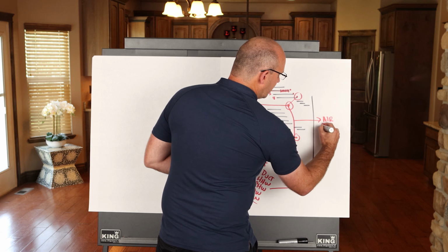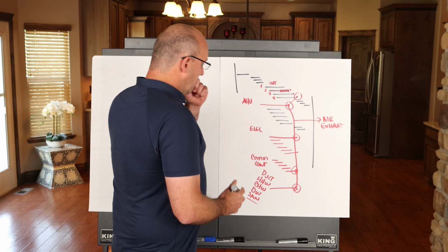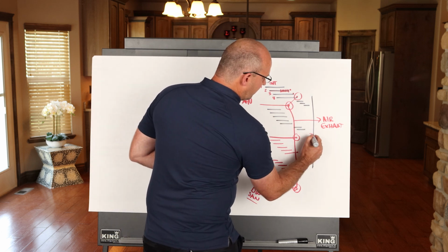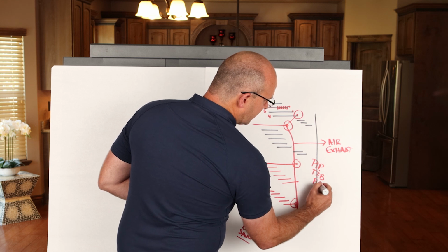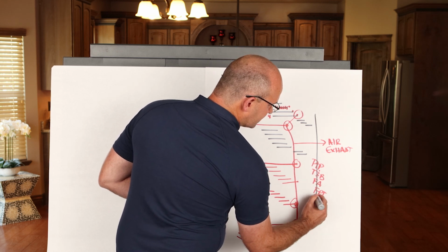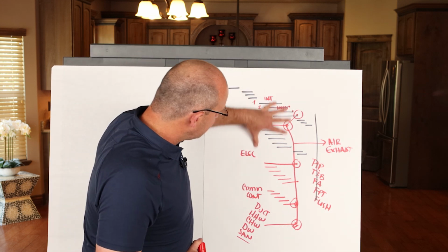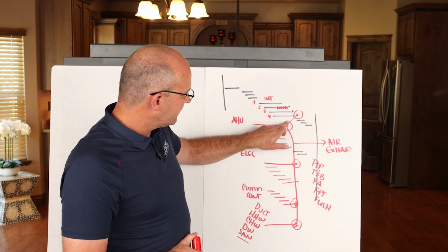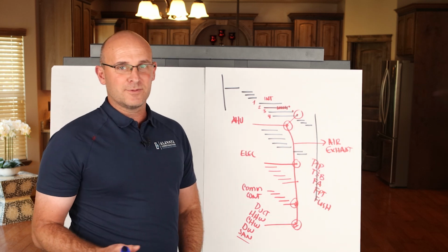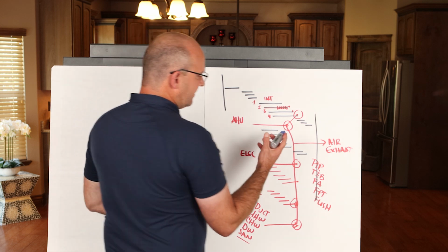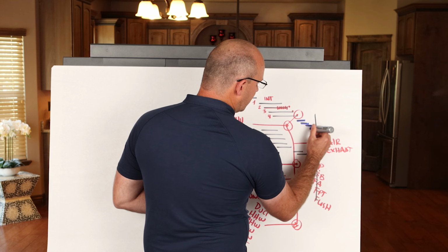Blowing air, doing the exhaust, obviously if you have a clean building, but then this allows you to do your overall point-to-point, your test and balance, your fire alarm integration, your functional performance testing, and then your building flush. So this has to be built into the overall structure, and you have to track these to release the rest of this. So typically in construction production plans, you'll see at the end of this that you have these commissioning activities. So it'll be like a couple of little bars out to the end.